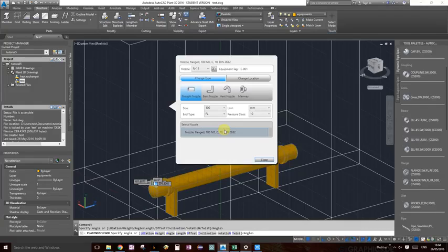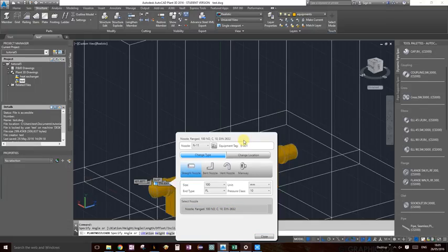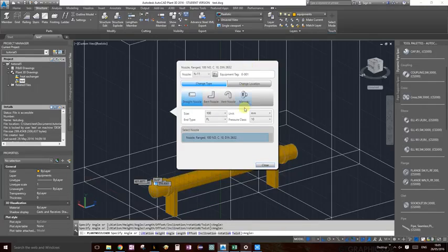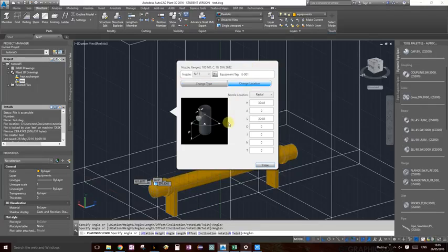Most of the time, again, either we would know the pressure and we would already have defined it, or you would have to choose it from some sort of catalog, depending on your design requirements. So on this, the only thing that should be showing up is the nozzle flange 100 ND C, 10, DIN 2632. Just select that and then head over to the change location.